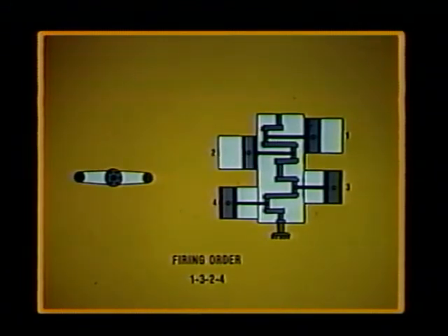This means when piston number 3 is on top of its compression stroke, number 1 piston is at the bottom of its compression stroke. The firing impulses are all 180 degrees apart, and all 4 cylinders fire in 2 revolutions of the crankshaft.